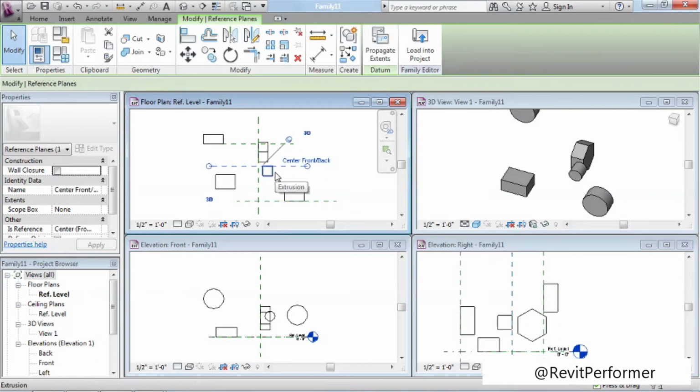This should have extruded up rather than down, because if I'm standing here, looking here, my left would have been up in this case, and it didn't prove to be the case. So some of the family templates that ship with the software, the default built-in reference planes, don't really respect the rule. With all the testing I've been able to do, as best I can tell, that's only really an issue with some of the built-in reference planes.